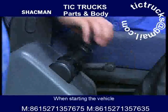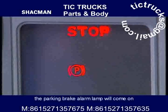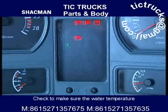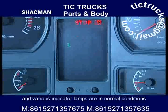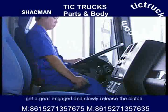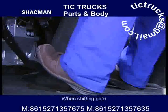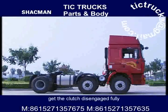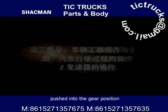When parking the vehicle, properly pull up the handbrake handle. The parking brake alarm lamp will come on. Check to make sure the water temperature, engine oil pressure, and various indicator lamps are in normal conditions. Get a gear engaged and slowly release the clutch. To start the vehicle, when shifting gear, get the clutch disengaged fully. The gear lever shall be properly pushed into gear position.